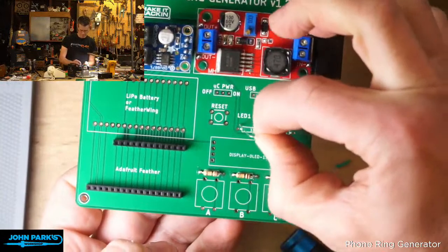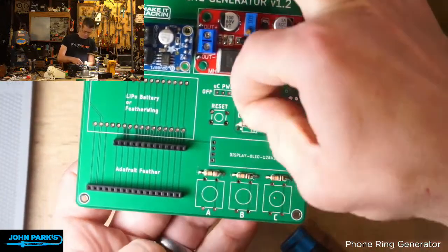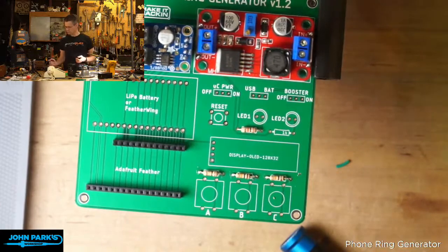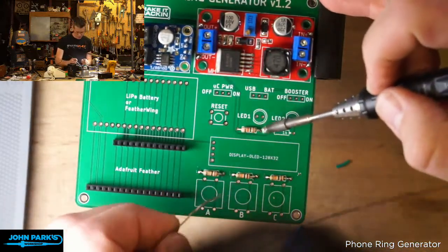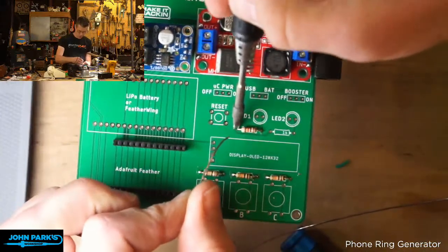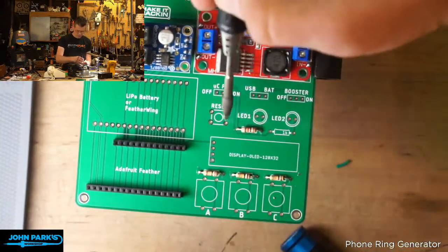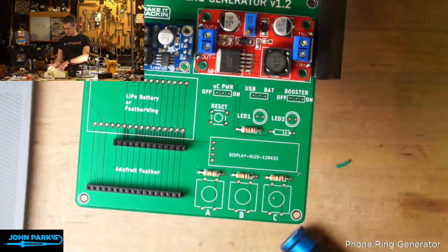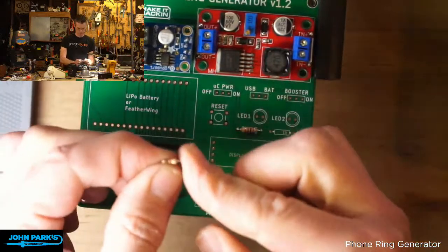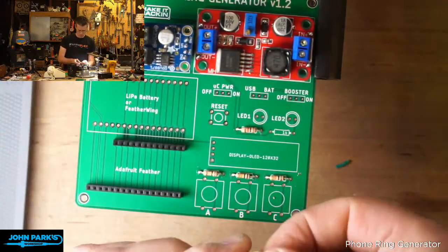I'll place these. Yeah, ideally your flush cutters won't bend the end. Also, putting them in from the top and soldering from the top means that you don't have the temptation to put them all in from the top and then flip them over and then solder them, which often leads to forgetting to solder some legs or things falling out. So that is another reason I do it that way, if you're wondering. There is no right way, there's just whatever you prefer for a lot of these types of tricks and tips. All right, gold band to the left.